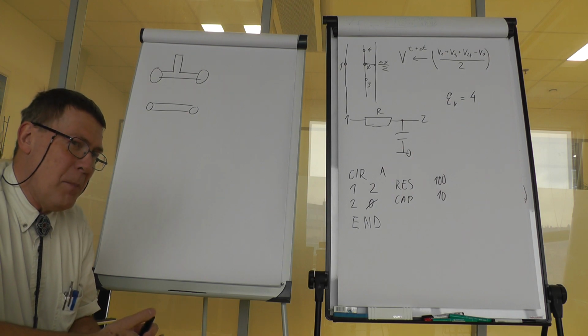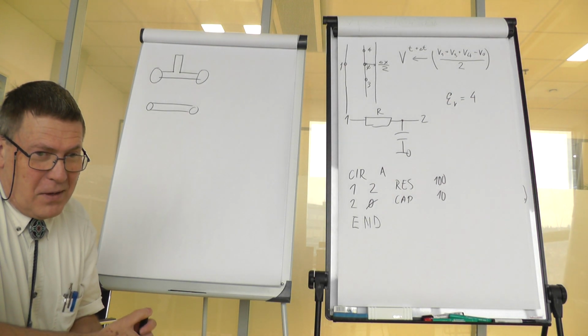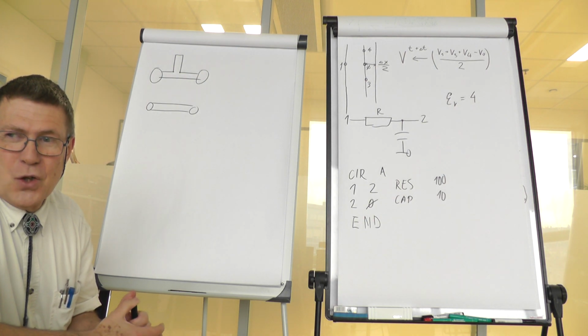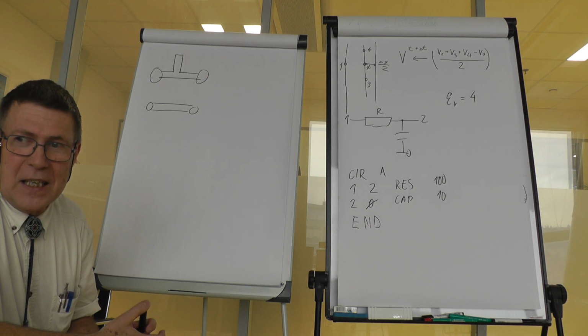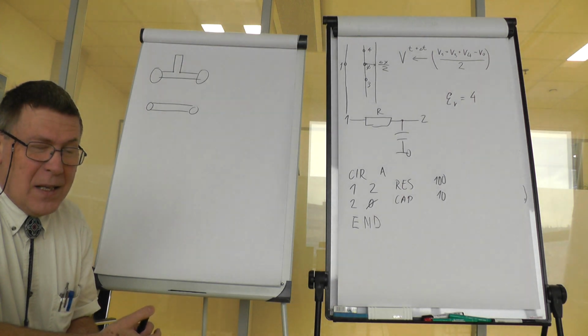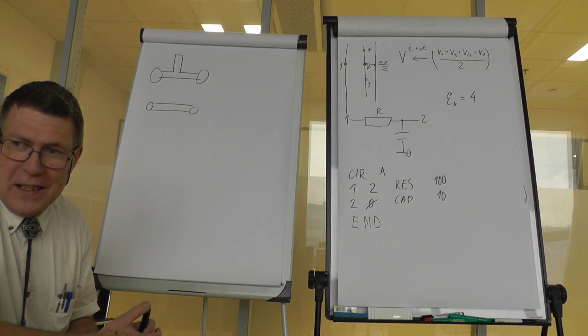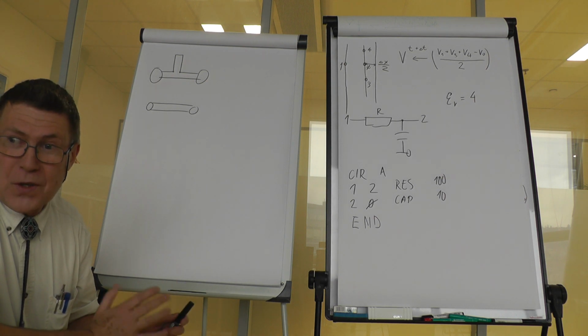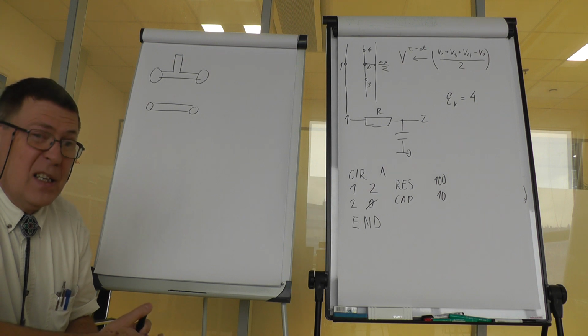Then again, there was a paper that investigated and compared several cases and has shown that yes, transmission line matrix gives you more solutions. Unfortunately, any of those solutions in addition to FDTD are non-physical, are false results due to discretization and solution methods.